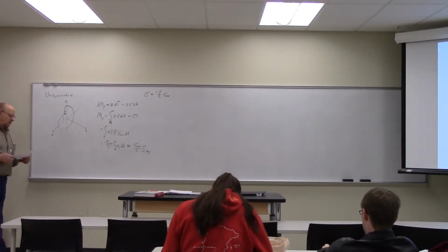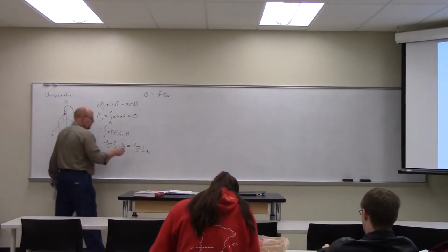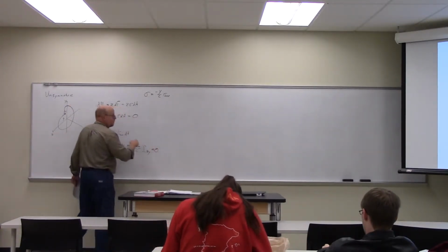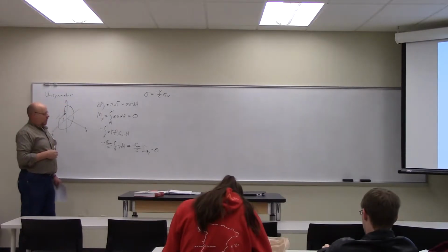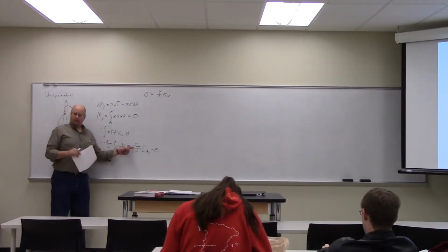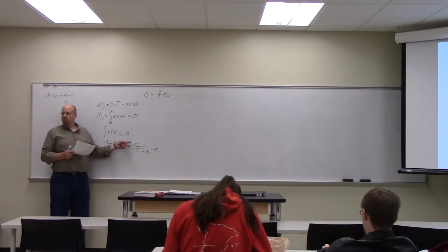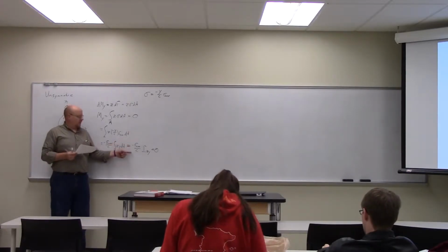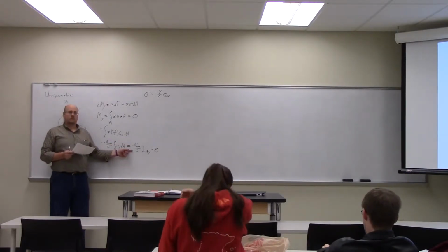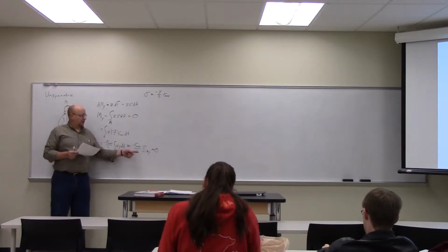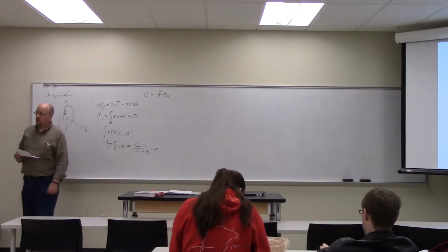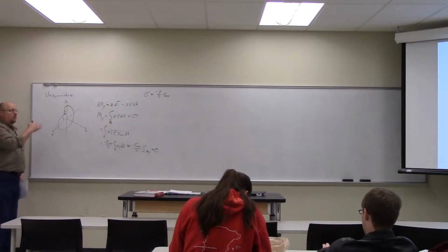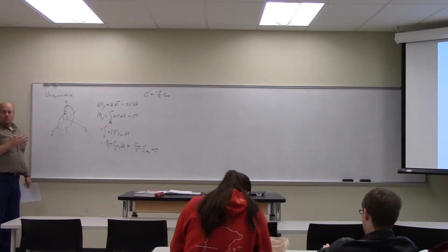And that's got to be equal to 0 in order to get pure bending. Is sigma max going to equal 0? No, not unless we have no moment. Is c going to equal 0? Not unless we have no bar. So IZY must be equal to 0. So in order to get pure bending for an unsymmetric bar, we must have a product of inertia, IZY, equal to 0.